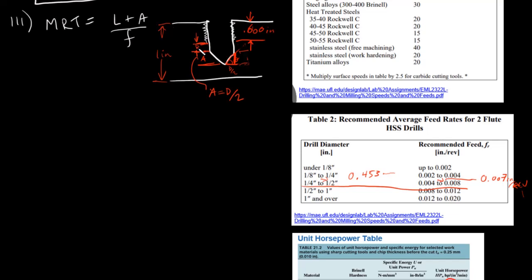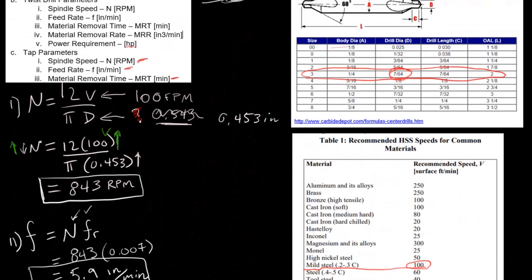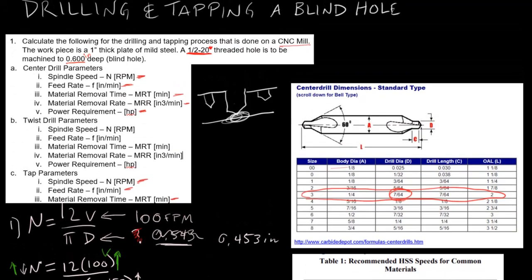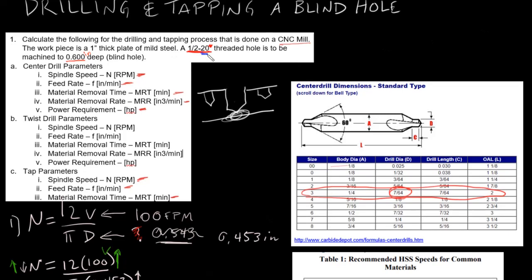I don't know what it's actually called. I'll switch my pen here to maybe, let's try blue. So B for blue. Okay, so B is 3 thread pitches. So 3 times your thread pitch. So again, we're going to go back to the question. And there are 20 threads per inch, and I see that right there.